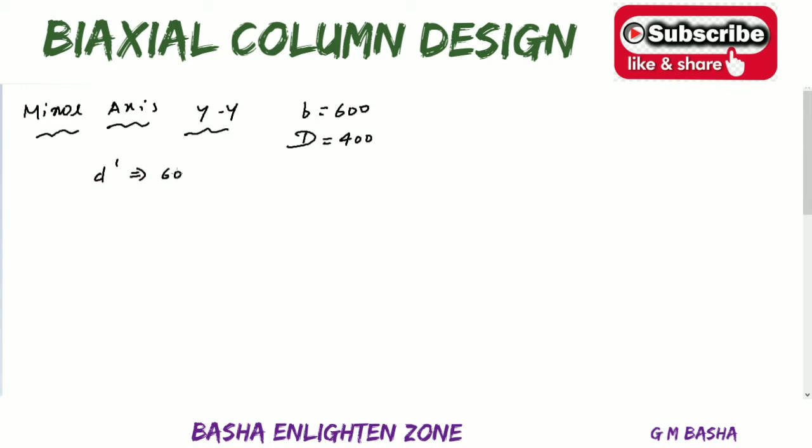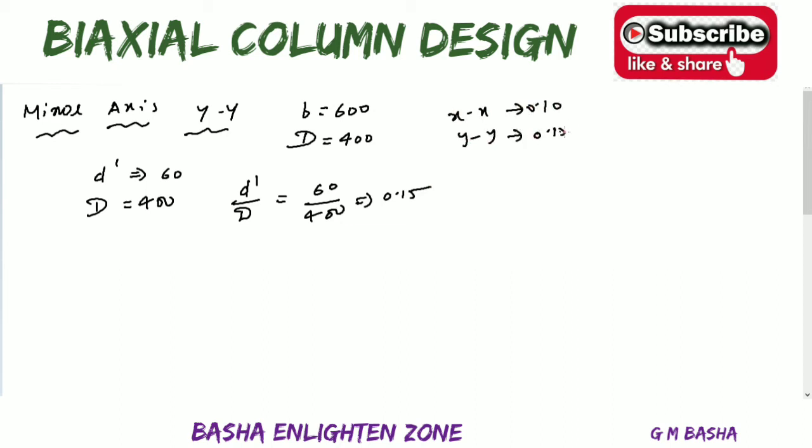What I told already, here we provided 20 bars like that. For that you can take 50 and you will get a different curve. If I choose d dash, I will get a different curve because the dimensions will be decreasing. Then d will be 400. So check d dash by d, around 60 by 400, which is equal to around 0.15. So for the x axis the graph will be 0.10, for the y axis the graph will be 0.15. I think it is better because in one problem itself we are using two graphs, so we will get two different ideas.